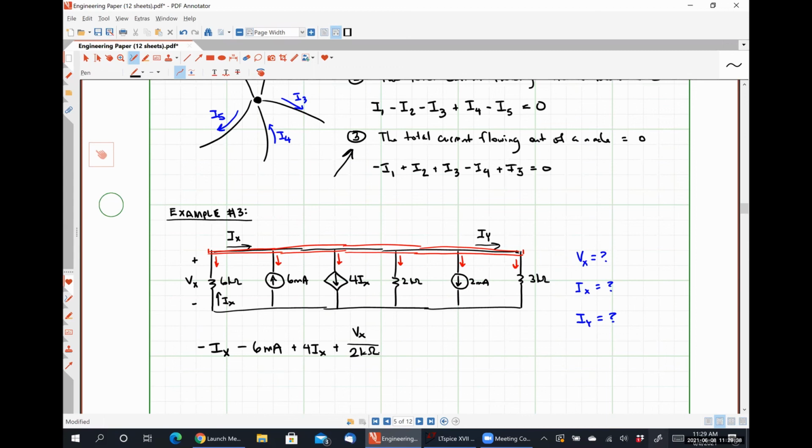Does that make sense? It's the fundamental definition of voltage, right? It's the difference in electric potential between two nodes. So I could just as easily say that this is Vx, because it is. It's the same voltage with the exact same polarity definitions. And so using Ohm's law, where the current flowing down goes into the positive polarity terminal, that means positive Vx divided by 2 kilo ohms is this little current right here flowing down.